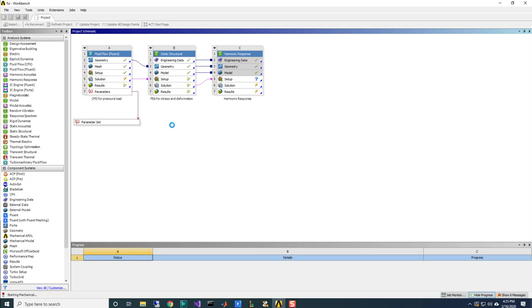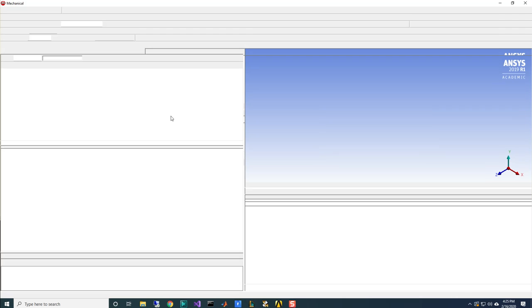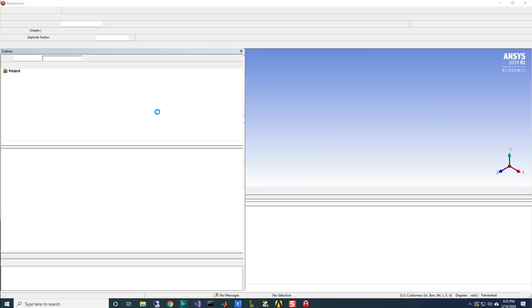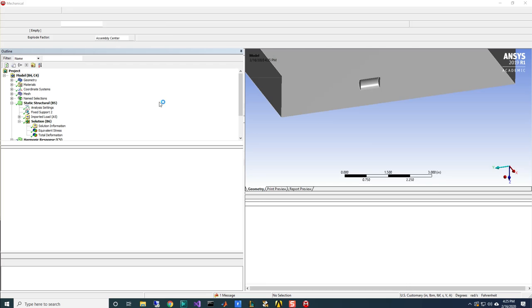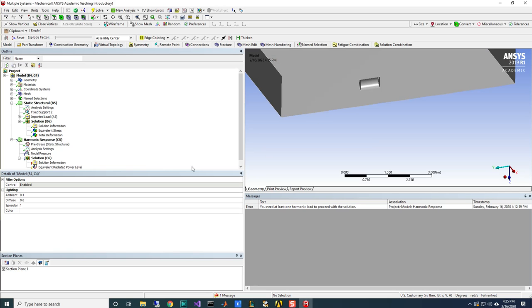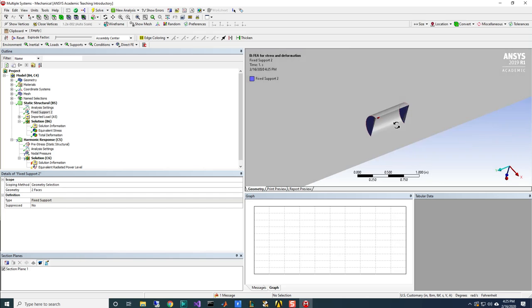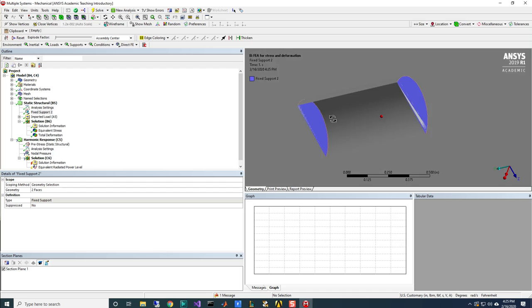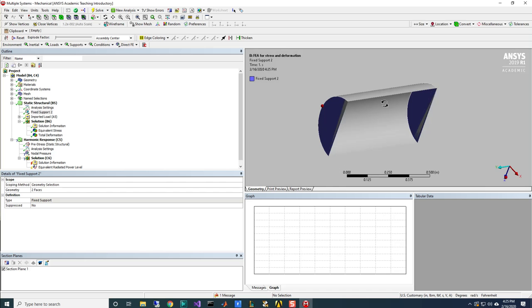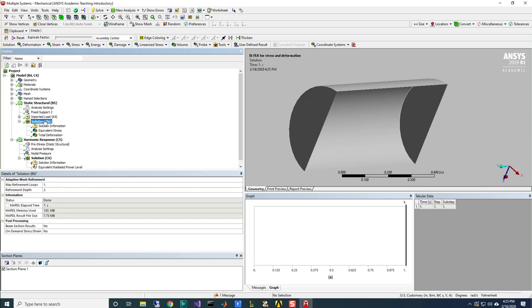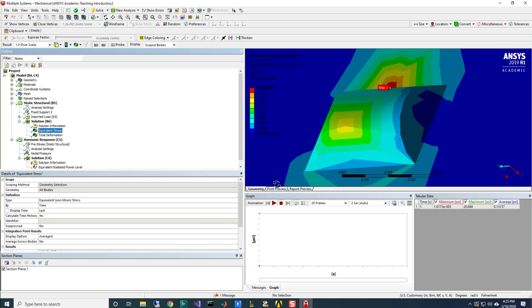The last thing I'm going to do here is set up some name selections that I'll use later. Inlet, outlet. If this were a Fluent application, I would also name the walls, but I don't need to here since I'm going into CFX and the default boundary condition will be adequate. So we've got a mesh for our CFD calculation.